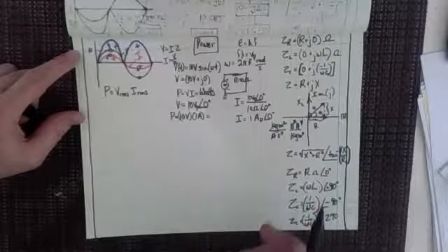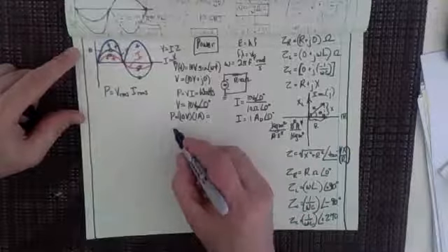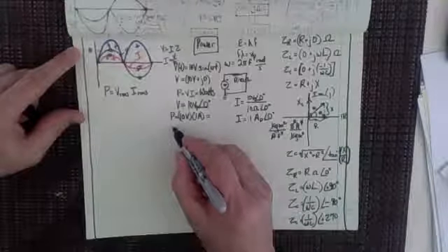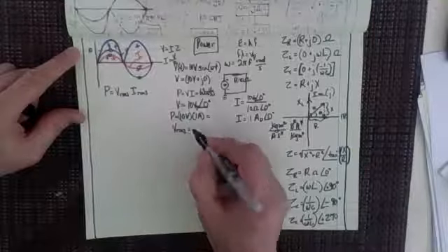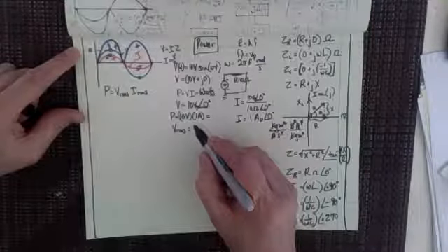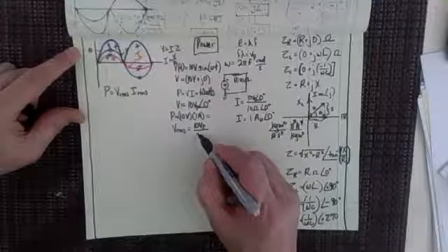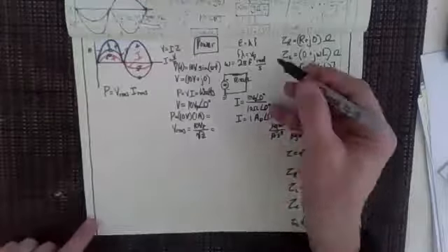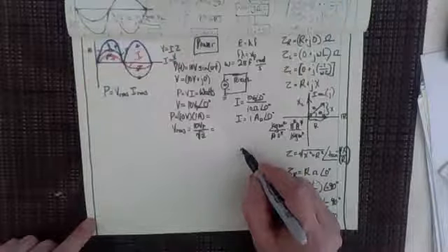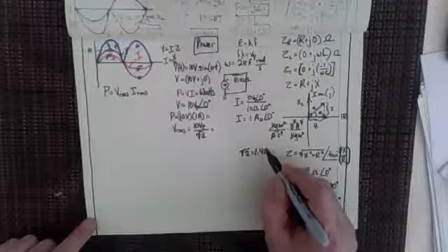And what is an RMS waveform as compared to a peak waveform? Well, we know that the VRMS is going to be equal to the peak, so 10 volts peak, divided by the square root of 2. And of course, the square root of 2, that's something that you should always know. The square root of 2 is going to be 1.414.